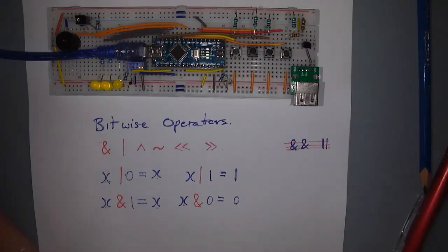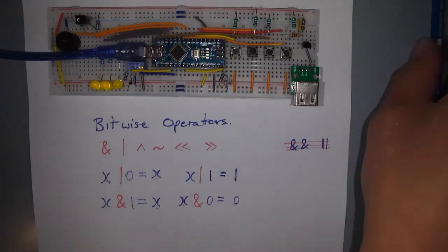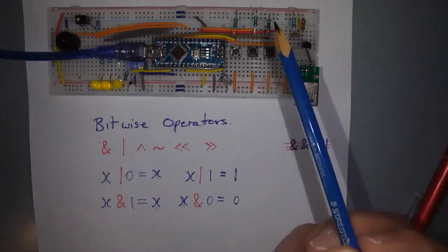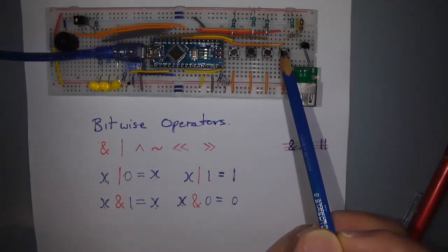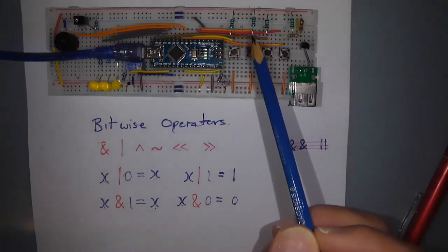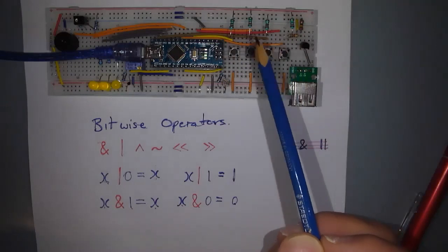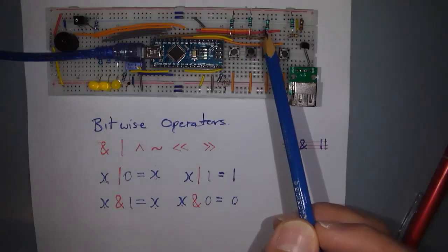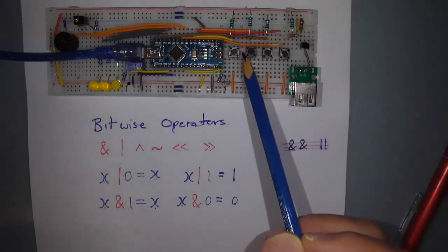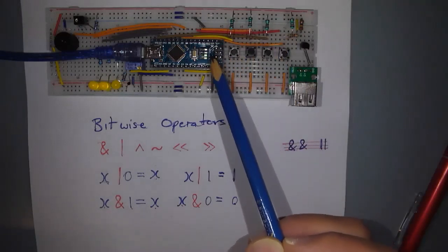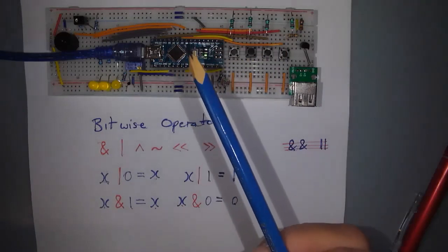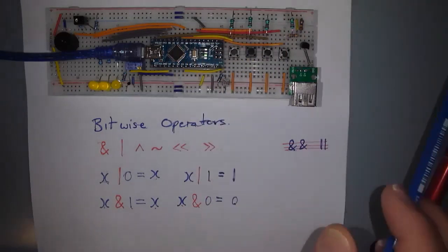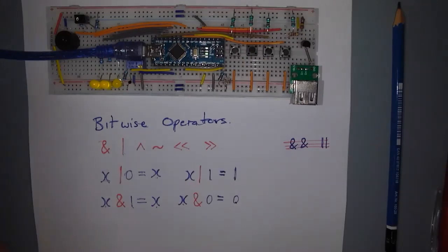So the reason this works in this instance is because, I'll draw your attention to my 4 switches here. What I've done is I have added pull-up resistors. I think I've used 15k resistors here. Yep, 1, 5, 0, 2 zeros. So I've used 15k pull-up resistors on here, and I'm not using the internal pull-up resistor. Well, that's actually quite important in this situation, and allows me to get away with this naughty thing that I've done here with this line of code.